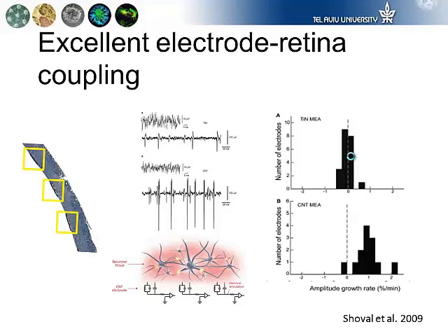And when you compare conventional titanium nitride electrodes with carbon nanotube electrodes, you see that titanium nitride electrodes basically have a certain base level of signal to noise. With carbon nanotube electrodes, we see that the signal to noise ratio just gets better and better. Basically, what we think is that it corresponds with this feature where the tissue, so if this is the tissue, it just gets more and more intimately contacted by the carbon nanotubes.